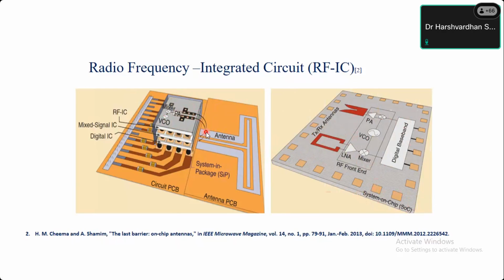Now these connectors need specific impedance matching also, right? The connectors anyway have losses. So you have to match those impedances, but here you can directly use the same impedance as the LNA and connect directly to the antenna. Generally the connectors have fixed impedance, nowadays whatever is available: 50 ohm, 60, 75 ohm.